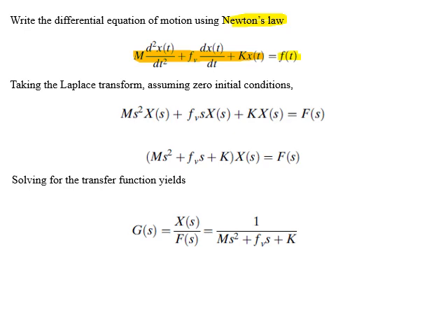So now we'll take the Laplace transform with zero initial conditions, which will convert our time domain relation into a simple algebraic relation. After taking X(s) common from the terms involving it and using the cross multiplication property, we'll reach our desired transfer function, which is X(s) over F(s).